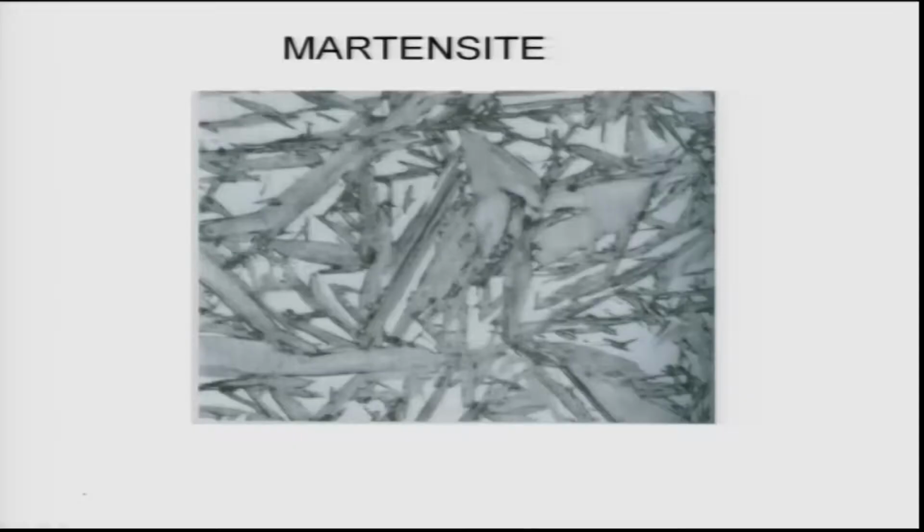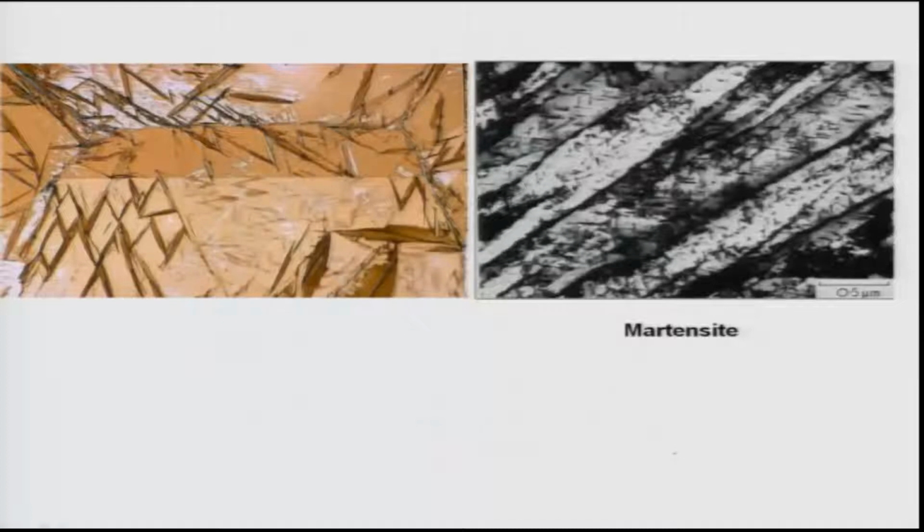all cases it happens. So, in the steels, martensite forms like plates or laths, and as you see here on the optical micrograph, these grey color features are basically martensitic laths. In between, the white thing is basically retained austenite, written gamma, and we term martensite, as I told, as alpha prime because it's the same as that.